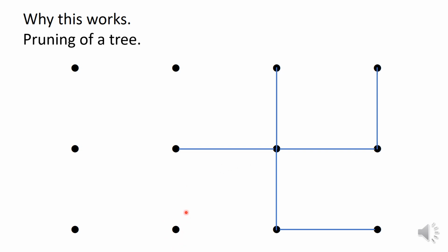Okay, we just had one unknown here. We can find the flow in that and keep going. And here we just had one unknown. Here we can look at any of these three nodes, find the flow in the branch with the unknown flow. Okay, we can find the flow here, and so on. We can keep going like that.